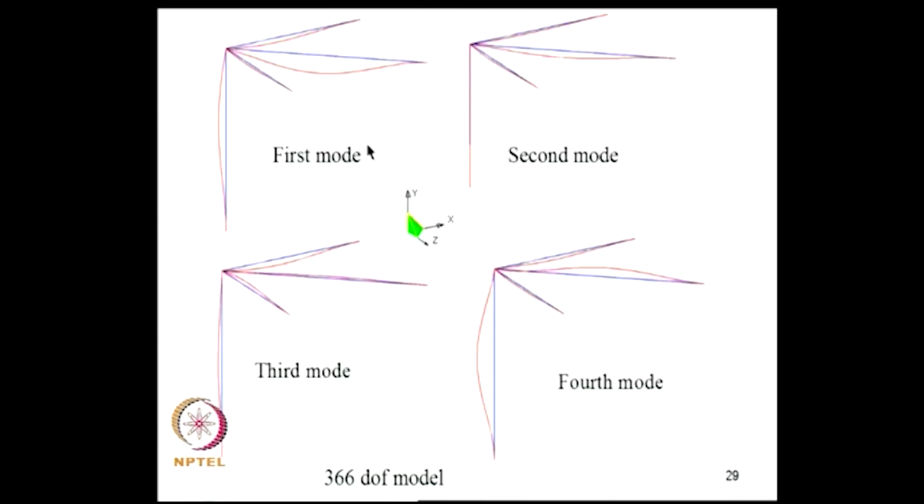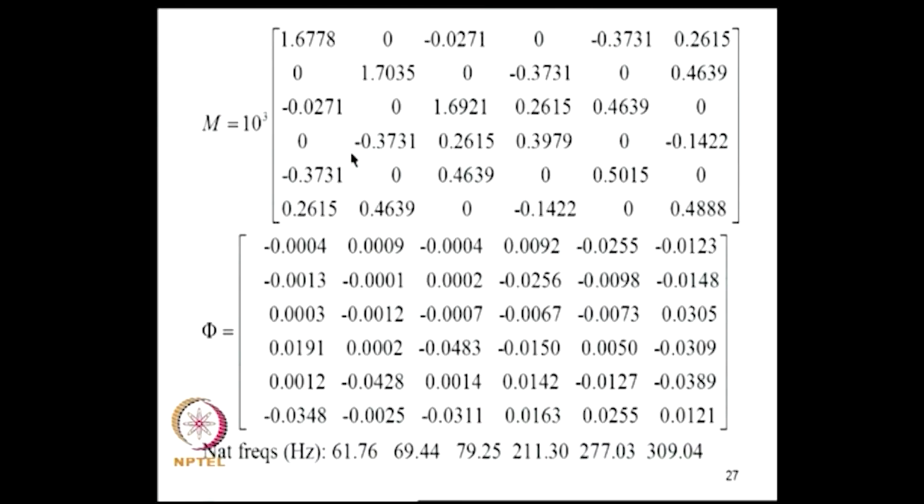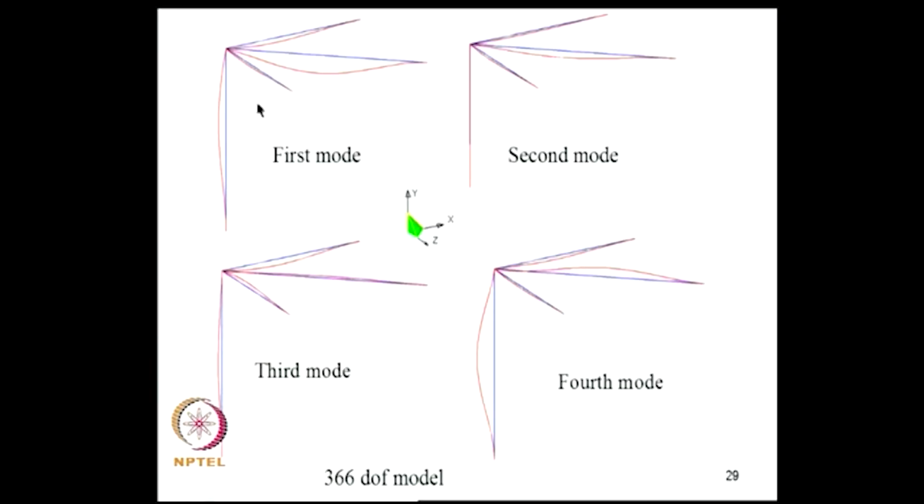are shown here. So, with respect to the discretization scheme that we have used, this is certainly a more exact result. You can see here that the first mode essentially consists of each beam behaving as if it is a propped cantilever. In the subsequent mode, they are all in phase, all the points are deflecting downwards, and in the subsequent few modes each of the elements will either be in phase or out of phase, and those modes will appear, and I have shown the first 4 modes. And mind you, the coordinate system for these graphs is marked here.